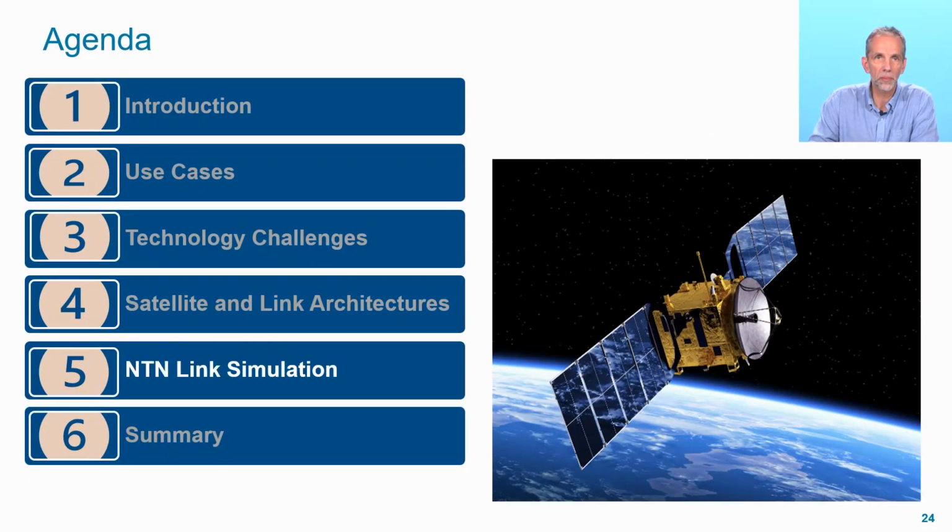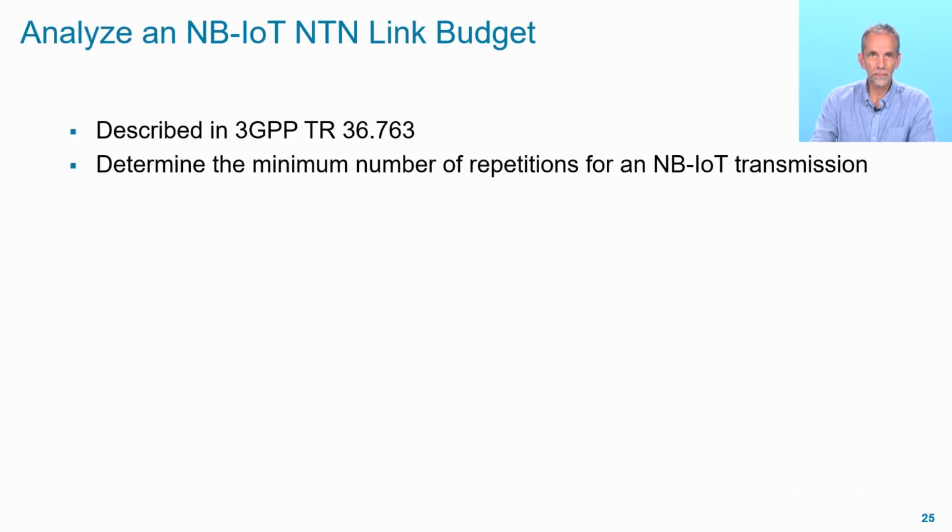Okay, let's talk a little bit about NTN Link Simulation. First thing, you want to be able to analyze a link budget. We've talked a little bit about link budgets already. And this is the first time we've introduced the narrowband IoT capability. But it does turn out that 3GPP is expecting NB-IoT to be used for NTN applications. So it's described in that technical report.